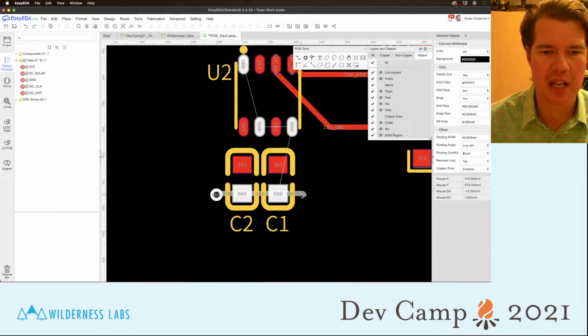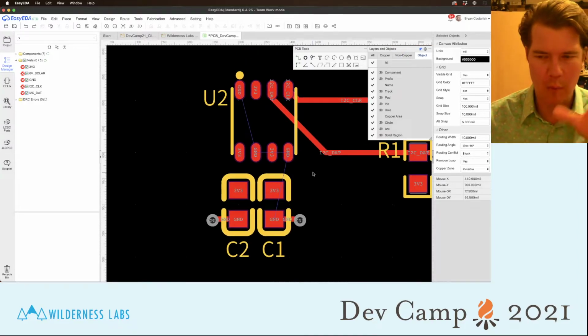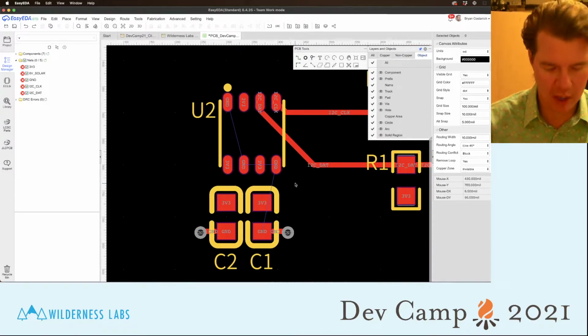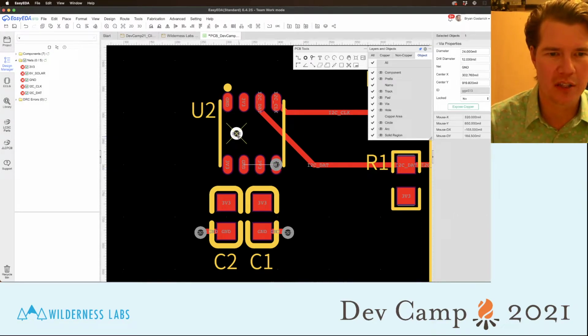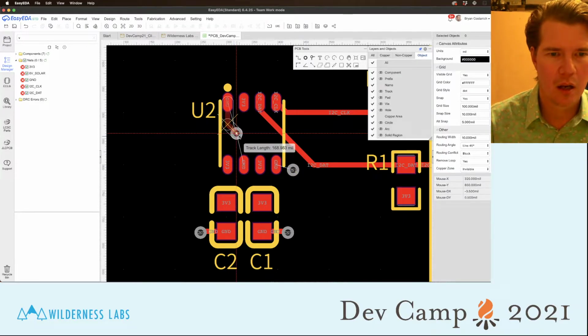It's not okay for decoupling capacitors, because doing that, tying them together, can make some weird electrical capacitance that we don't want. And I don't fully understand what it does, but I just know that you don't want to do that. And vias are cheap. Vias are free. They don't add any money to your board. So you can put all the vias in you want. In this case, we're going to share. Those two can share, and we'll just tie them like this.